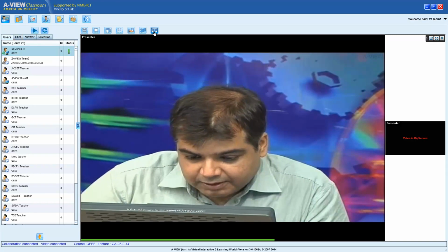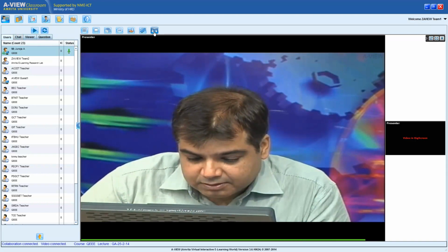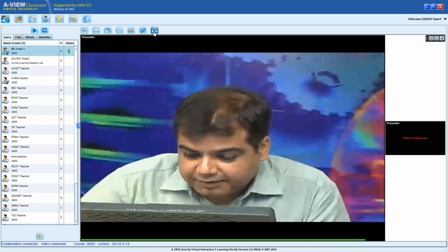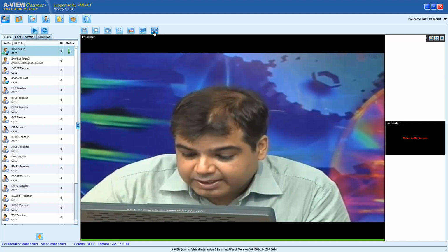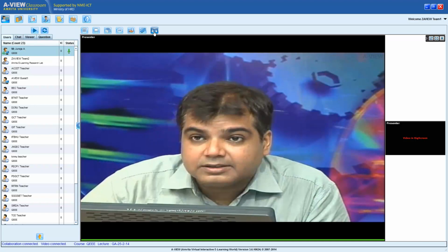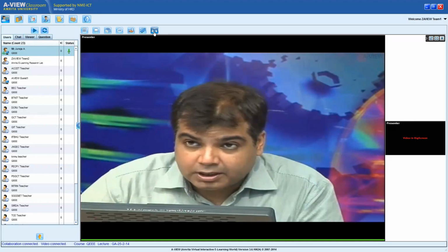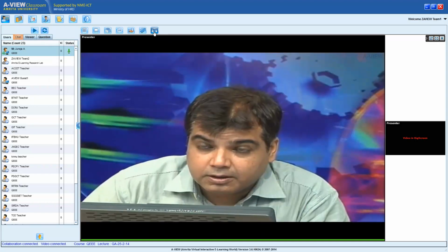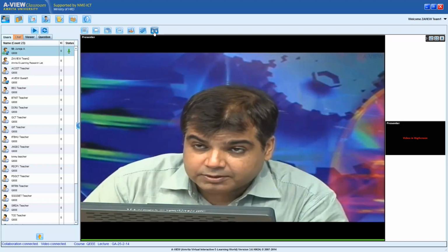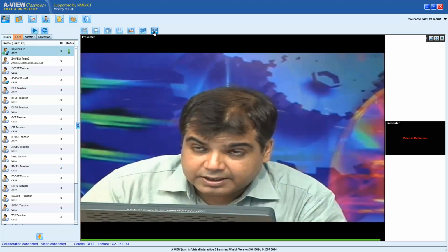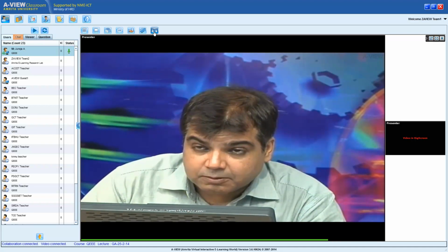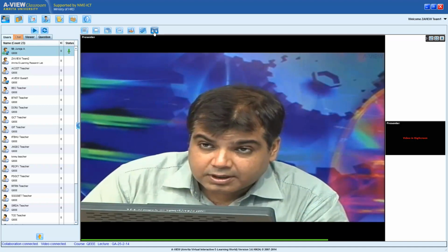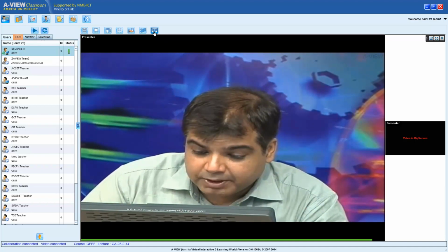So we looked at this section on capillarity. In fact, there was a photograph on the first slide. I missed explaining this. This photograph is from Niigata, 1964, I think. It shows how the water had played a very significant role in the liquefaction. We'll come to liquefaction, but it tries to explain how the upward movement of the water would cause the effective stress of the soil to become zero.